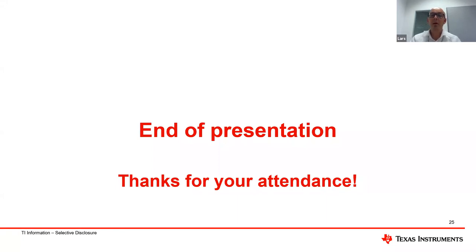So before you build in a component, have a look at the failure mode distribution. You say, okay, if this resistor goes open, what consequence has it for me? If you, for example, have a resistor divider and the lower leg to ground opens, you have a full voltage to the next circuit. This is a problem, right?